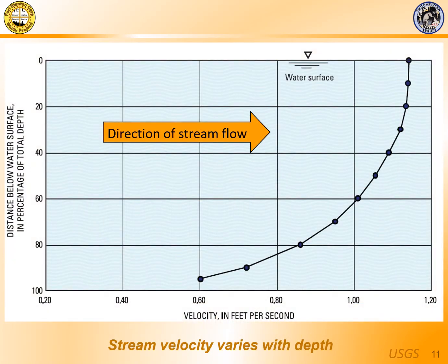Vertically, how do we deal with the different velocities? Well, here we are at our diagram that shows a stream velocity distribution in profile again. The velocities are highest near the top of the stream and lower near the bottom of the stream. And it's been determined experimentally using laboratory experiments and in many streams that the best place to measure the velocity is at about the 0.6 depth.